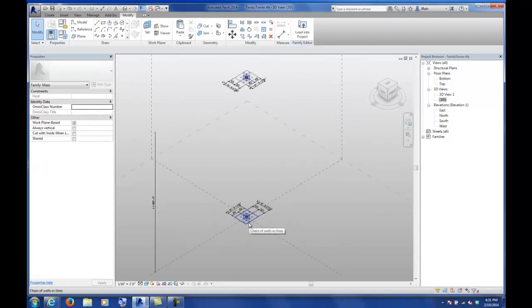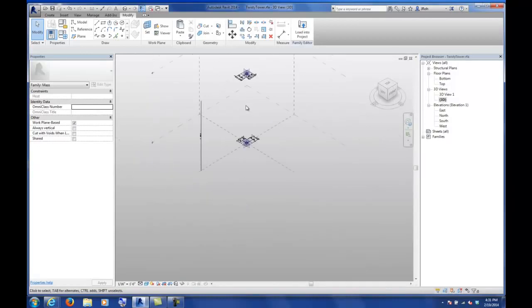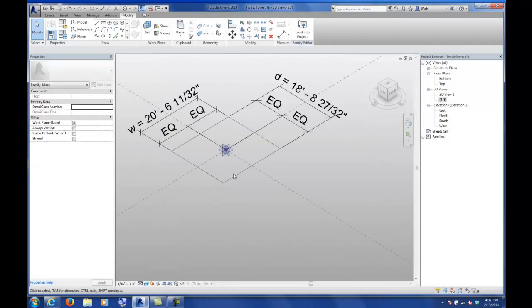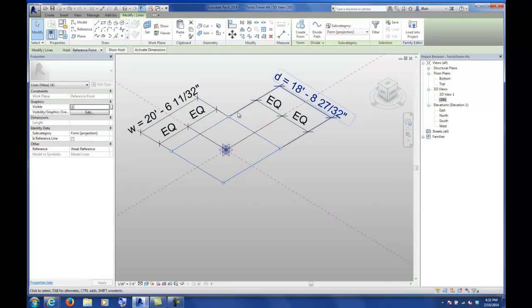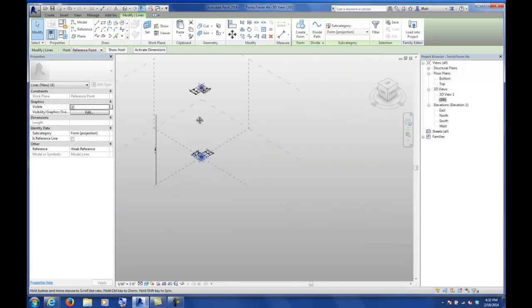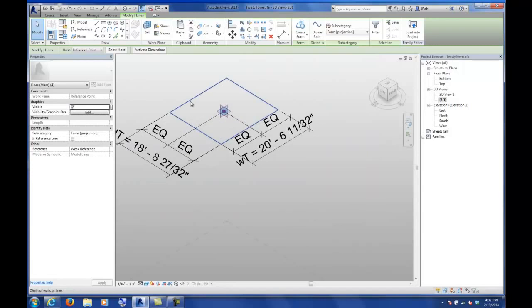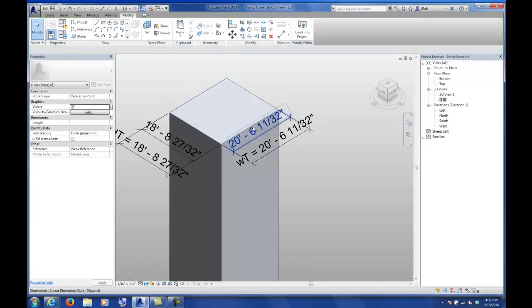And then when you've got all of that set up, you can zoom in and select the wireframe that's associated with the bottom. And we can go to the top and hold in the control key and select that wireframe and then choose create form and your solid form.